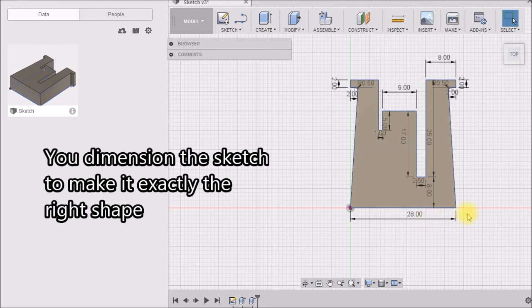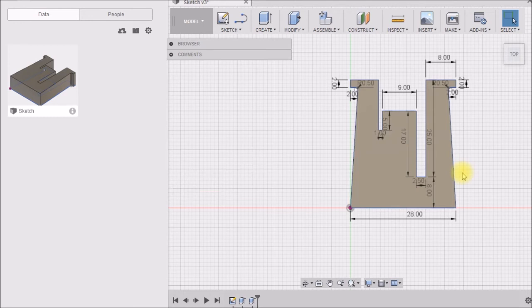That was the final thing I learned, was you really have to be careful on where you put your dimensions, because if you put them in the wrong place, things inside will start changing. You know, dimensions that matter, if they're referenced to something that doesn't matter, they can change. And the idea was this clip has to fit around that light, and the light doesn't change size. But if I want to make this clip 10 millimeter deep here, or I want to make this a little bit wider, a little bit narrower, that doesn't affect these internal dimensions. So anyway, that's kind of the things I learned, was really be careful when you're doing your sketch.